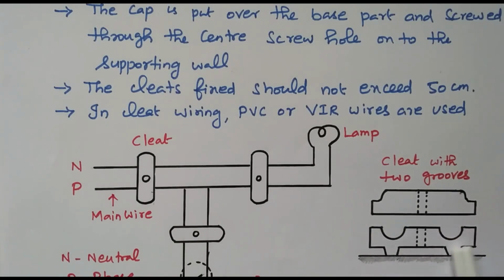See, this is the clad available. There are 2 parts here, the top one and the bottom one. This is the screw part. Here the hole is available, and in that the wires are placed. The conductors are placed in these 2 places. Then the top portion is placed and the screw is given so that it becomes tight. So this is the main part of the clad wiring, having 2 parts, the top one and the bottom one. Through this hole the conductors are placed.